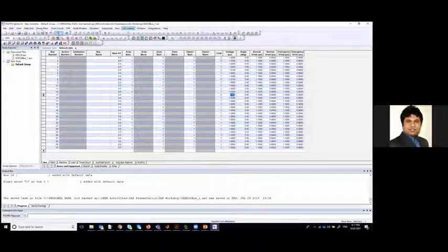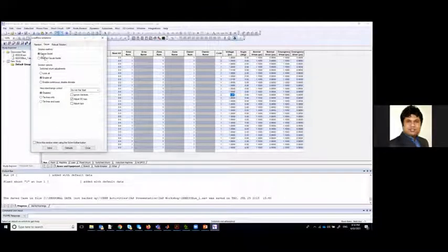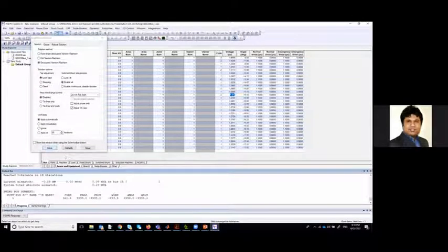So if I do the power flow of this one the same way, let's use the big one. So let's use Newton-Raphson, decoupled Newton-Raphson. Okay. So even with this large system, we reach the tolerance within 13 iterations, okay? So that means it reached the tolerance within few iterations. So that means it converged.